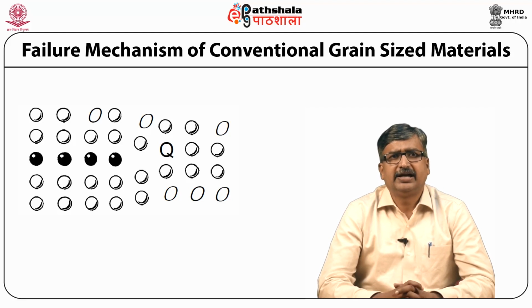Another kind of mechanical failure is the brittle to ductile transition, where the stress strain curve deviates from linearity, as shown in the figure. In this region, the material is irreversibly elongated before fracture. When the stress is removed after the brittle to ductile transition, the material does not return to its original length.